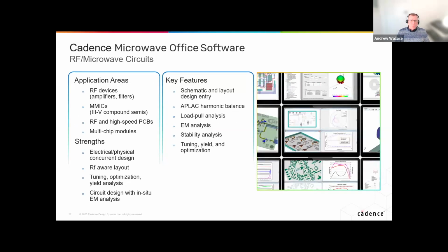So the most widely used product from the Cadence AWR family is Microwave Office, commonly used for the design of MICs, that's microwave integrated circuits, MMICs, monolithic microwave integrated circuits on exotic material, but primarily RF PCB boards and modules. You've seen one just a few moments ago on a slide a little earlier. The technology type is simply a process design kit or a PDK that we load on top of the software. And that's exactly how we load the Modelithics library into the tool. We do file new with library. I'll show you that in the software tool itself in a few more slides' time.